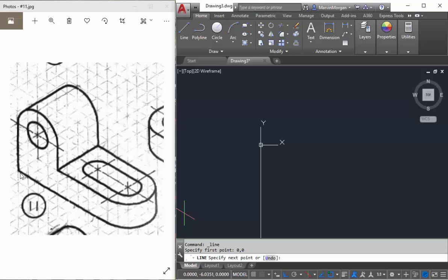I want to begin by going in a downwards direction, and I want to go the distance from this corner here, following my mouse, all the way down to this particular line. This line stops right here at the center point of this circle here, and so that's a critical point for creating our curves. That will be a distance of 9 units. So I'm going to type 9 and press enter.